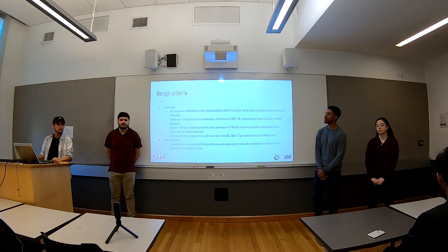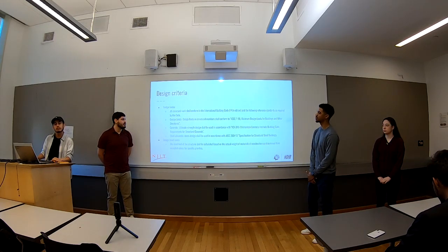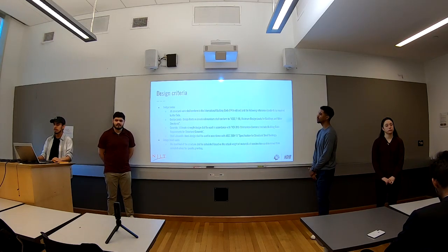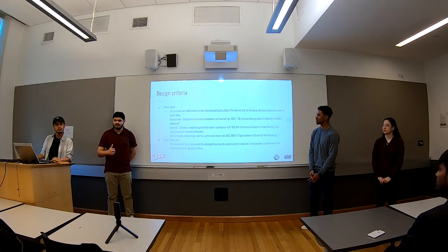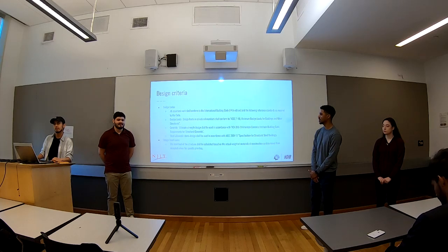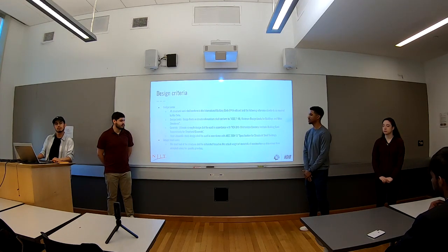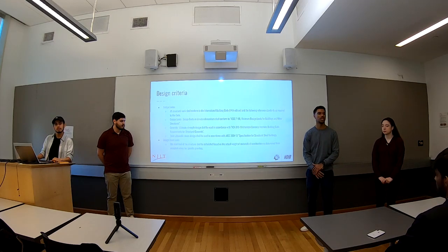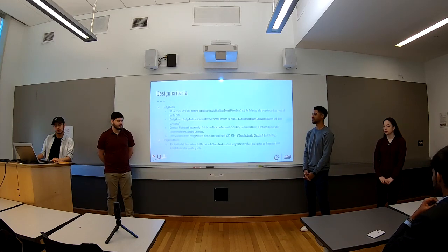So these are design criteria, the same design codes that we all have to follow for our 40-story buildings. All structural work shall conform to the International Building Code. We're going to follow ASCE 7-10, minimum design loads for buildings and other structures, ACI 318-11, and AISC 360. Yeah, all standard design codes that we all have to follow. And we're going to be using them throughout our design.